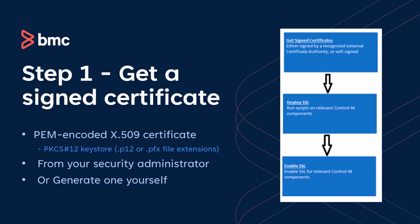For production environments, BMC strongly recommends using a certificate signed by a trusted CA. But if you're doing a proof of concept or a lab demo, you can use the default self-signed certificate generated from the Control-M Configuration Manager.